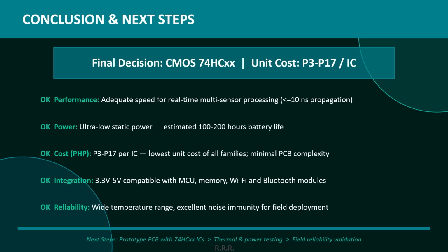And reliability. CMOS operates across a wide temperature range and provides excellent noise immunity, giving us confidence that the product will perform dependably in real-world home environments. Our next steps are: build a prototype PCB using 74HCXX ICs, conduct thermal and power consumption testing, and then move to field reliability validation before final production sign-off.